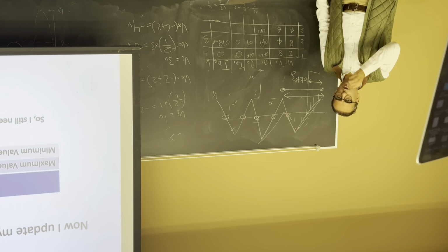And not only because of this, because you always get a lot of noise here. If you sample in the middle, there's a chance that you are away from the noise. Interesting. That makes sense. So this is the art of firmware and computer engineers, to enable digital control of the system.